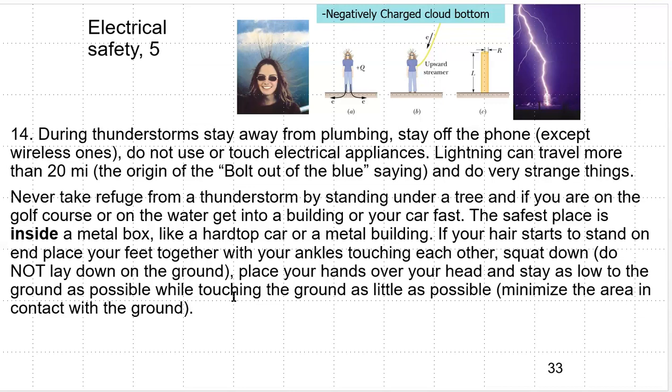If your hair starts to stand on end, place your feet together with your ankles touching each other. Squat down. Do not lay down on the ground. Place your hands over your head and stay as low to the ground as possible while touching the ground as little as possible. So in other words, minimize the area in contact with the ground. You don't want a ground current going through you.